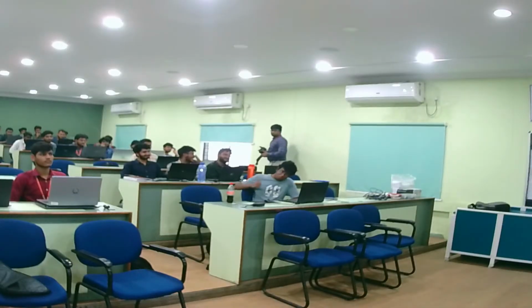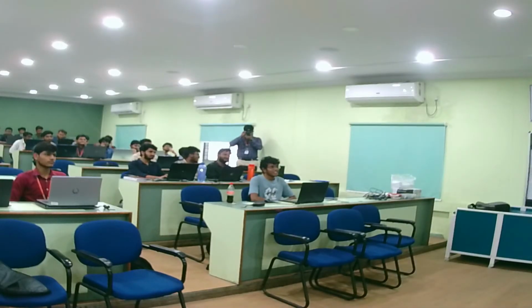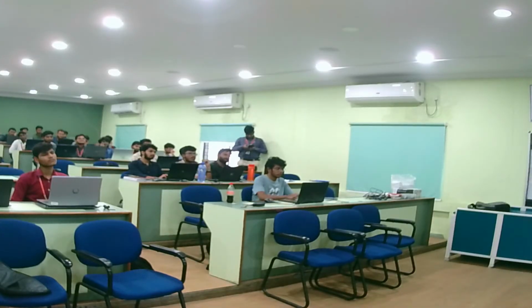I will go to my front panel. I right click on numeric. I'll check the numeric control. I'll put it as input A, input B. I'll check the numeric indicator. I'll give it again a name.